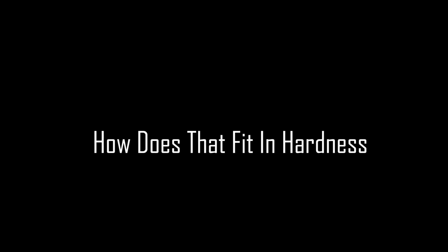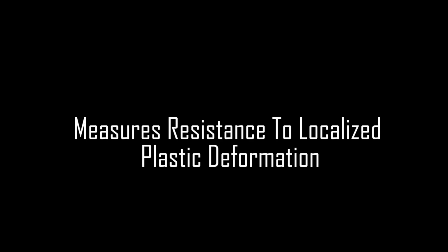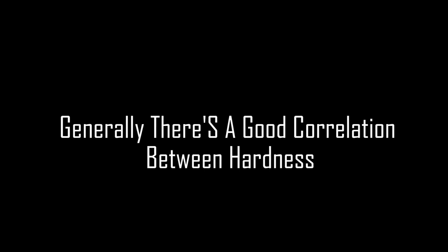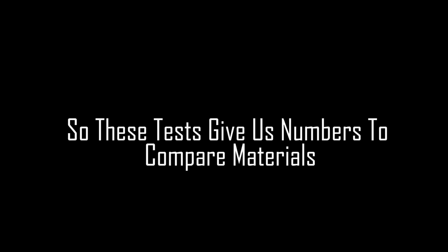We also hear about hardness testing. How does that fit in? Hardness measures resistance to localized plastic deformation, like scratching or denting. Tests like Rockwell and Brinell in Table 6.6 press a standardized indenter into the surface. And harder usually means stronger. Generally, there's a good correlation between hardness and tensile strength. It's a relatively easy test to perform. So these tests give us numbers to compare materials.